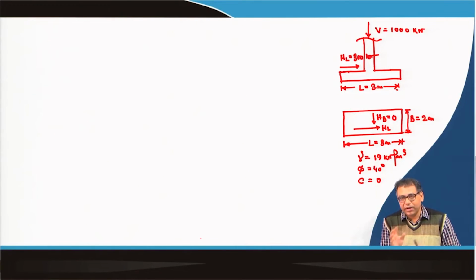Okay. So, if a triaxial phi value is given, and you want to use it under plane strain condition, or in other words where the length of the foundation is higher than the width of the foundation, then we have to modify the phi value.